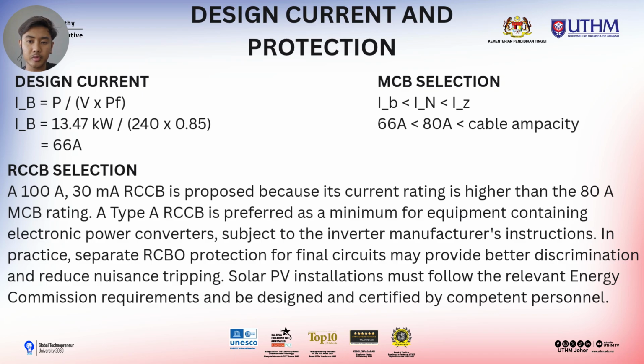For the design current, we use the standard formula and the calculated value is 66 ampere. Next, for the MCB selection, we follow the condition IB is less than IN and IN is less than IZ. Therefore, we selected an 80 ampere MCB because it is higher than the design current and still within the cable capacity. Lastly, we selected a 100 ampere 30 milliampere RCCB to provide protection against leakage and electric shock.